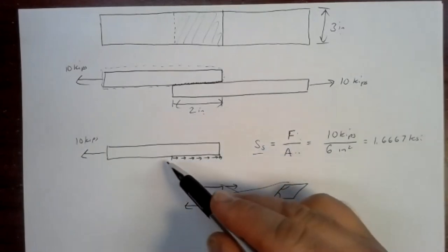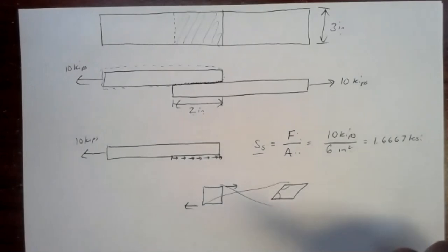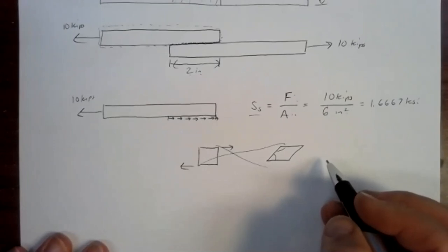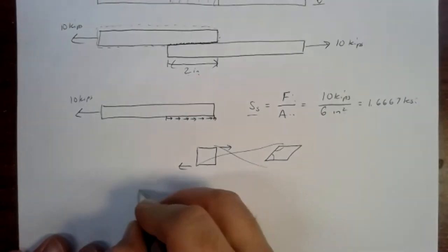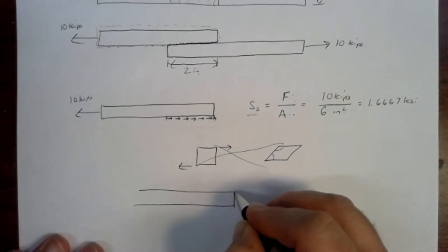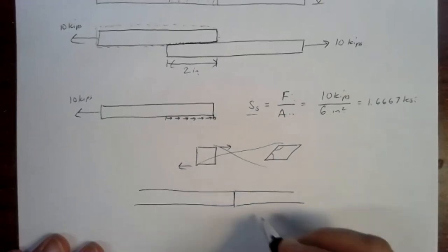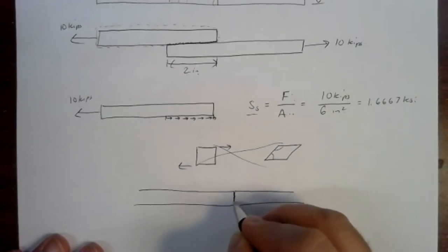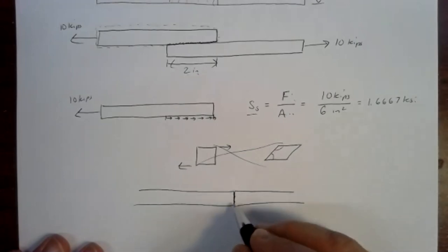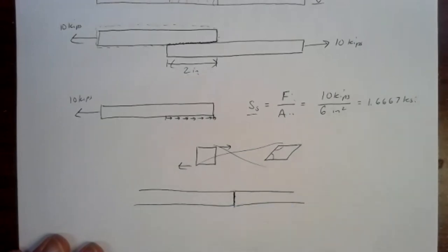If I could increase the area of that lap, I'd lower the stress. That's exactly what we do, for example, in doing glue joints with wood. If you remember with glue joints in wood, if you just have a butt joint like that, all your stress is on that area right in between there. And it's not too hard to cause that to break, to exceed the limits on that